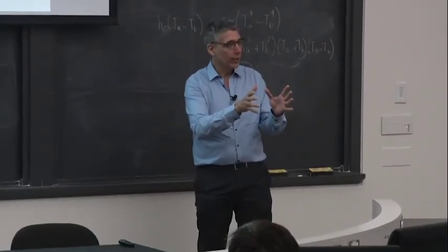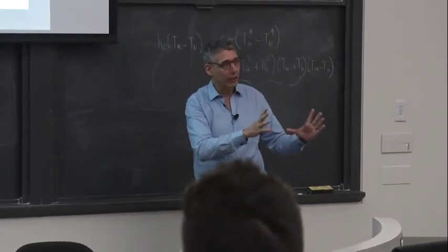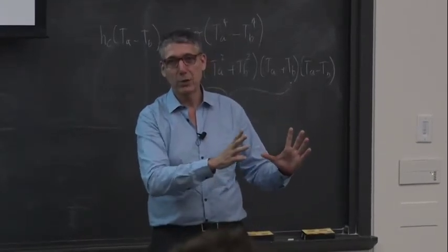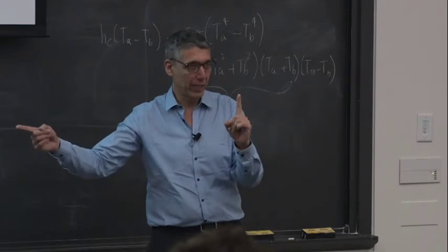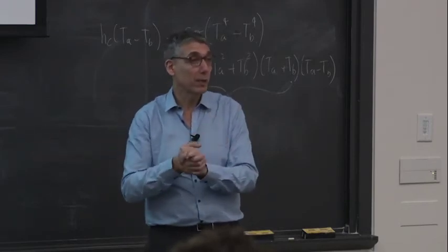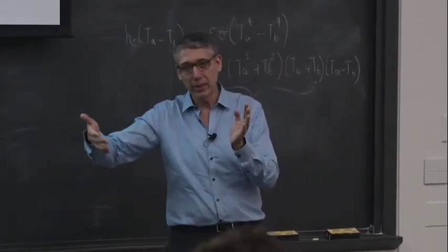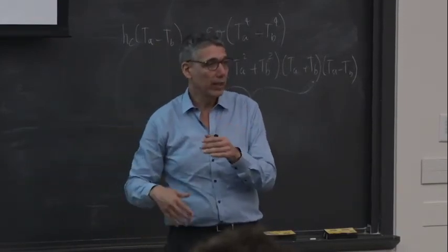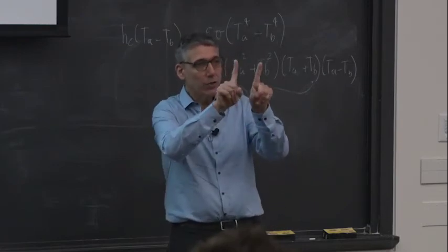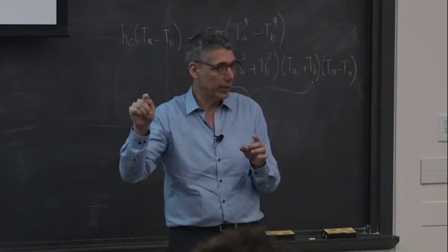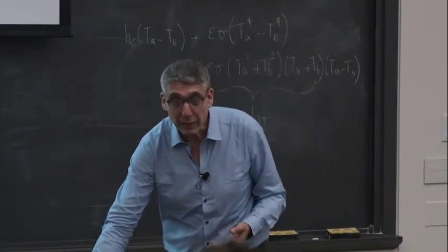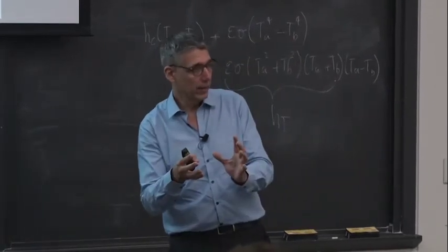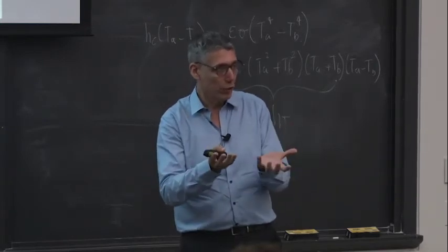Now, this is the mind of an individual that thinks with very clear and solid theoretical arguments, but has an incredibly astute practical motivation. With one test, he's getting hundreds of data points. He only has to run the flame spread test once. And he has so many data points that he can do his line fit perfectly and find the value of phi without even having to repeat the test. Because depending on how far apart he puts the two sticks, he can create more and more data points. So with one test, you pretty much have everything that you need. He brings the whole theory into the test in such a way that the test represents a physical concept that is meaningful.